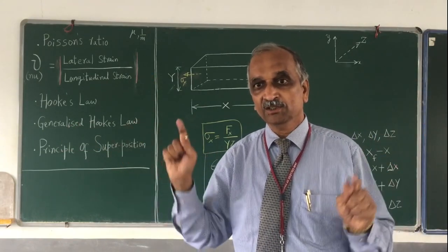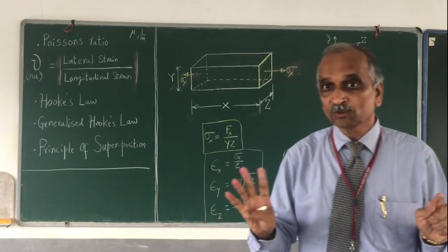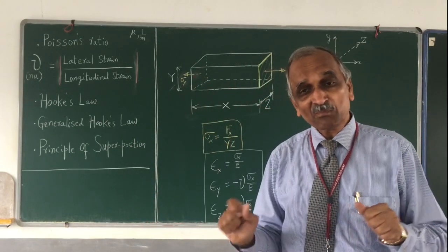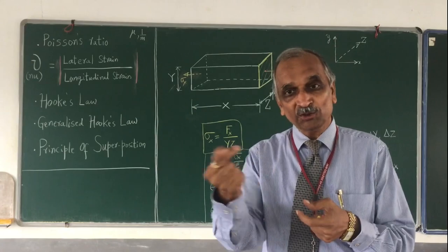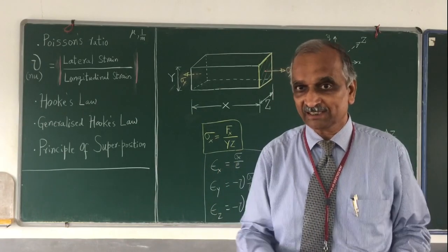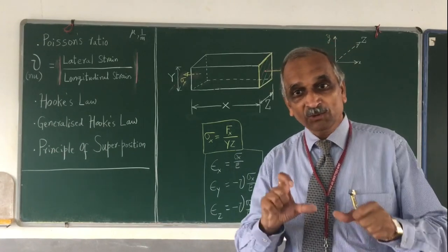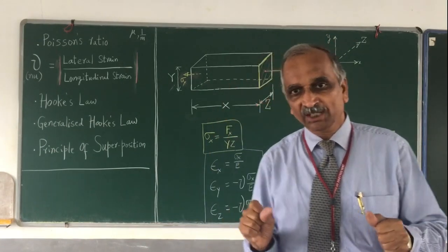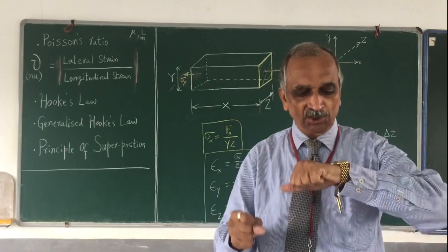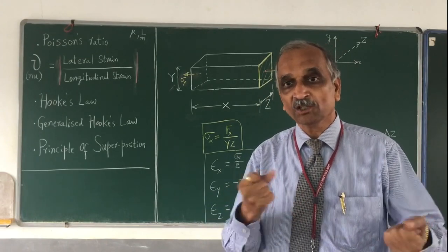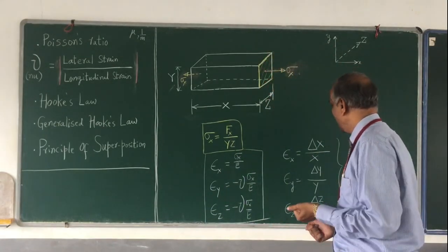The normal stresses are not going to change the shape of the body. But the shear stress, which I am going to introduce shortly or maybe in the next class, will change the shape of the body. That will distort the shape of the body. That is why shear stress is also called distortion stress. But here I don't have that.